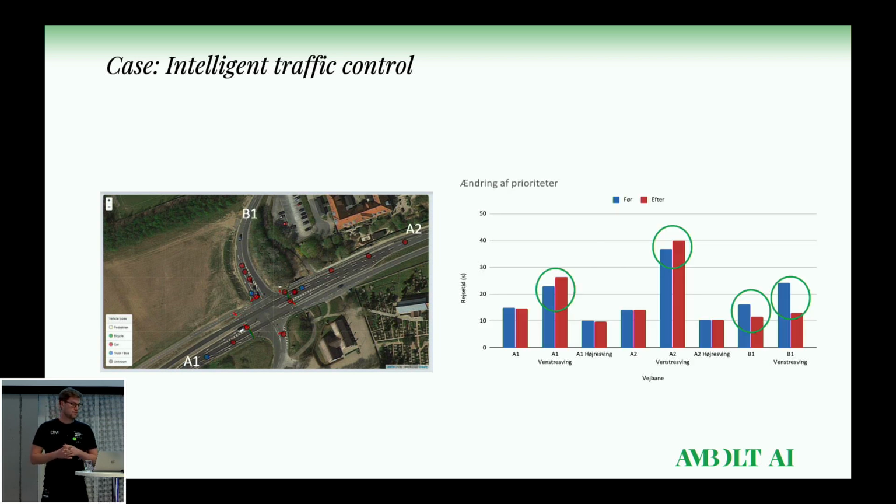And the day after, he was actually able to send the principal of the school a diagram like this, where you can see that the priority is shifted, where now it takes a little bit longer for cars on the left turning lanes, so that would be here and here. And the new capacity is then given to the B turning lane, so that means our priority was given to the school instead of the left turning lanes on the main direction.